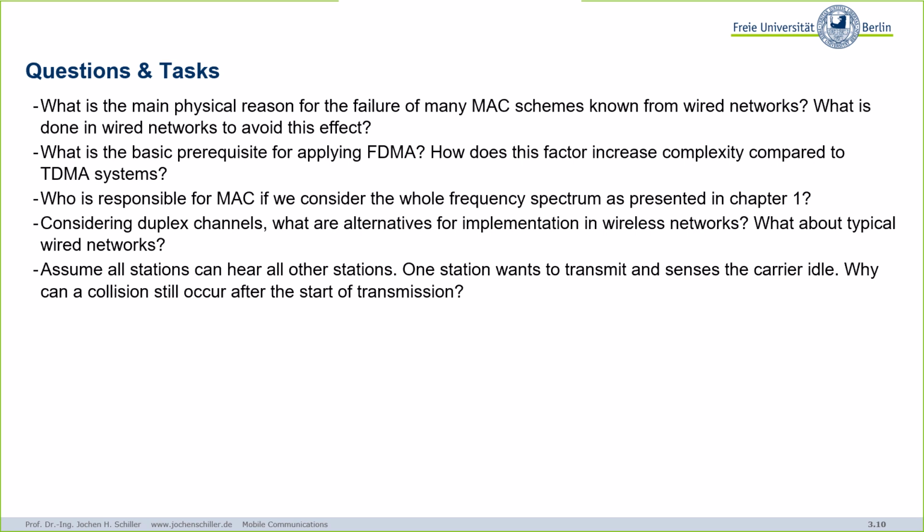This is exactly what you do in the classical digital telephones, ISDN, whatever. This is called echo cancellation. So you know what you send, and while sending, you will receive the signal from the other side plus the echoes of your signal.